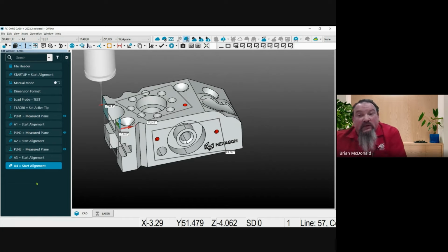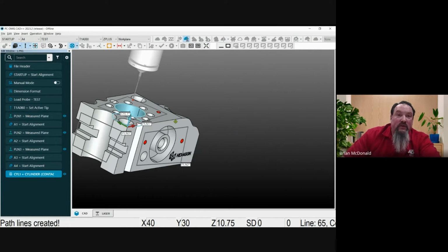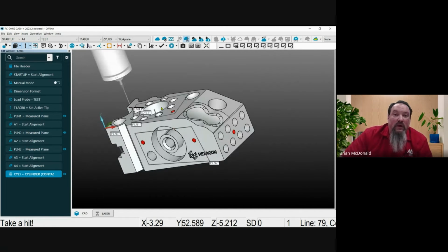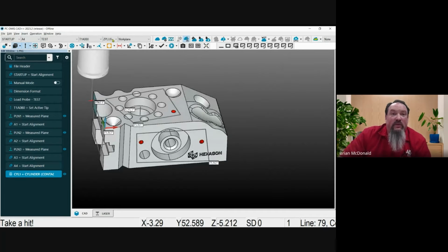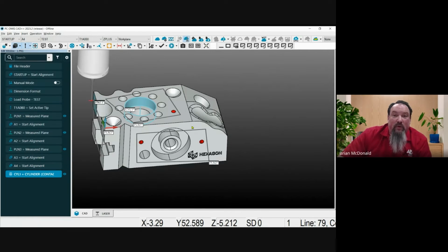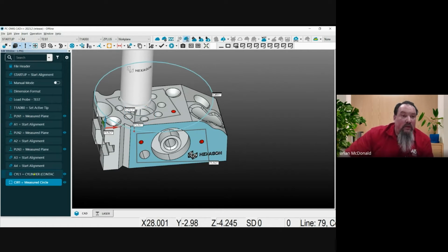The question is, can we use auto alignment with only planes, or can we use it with points, lines, and planes? You can use it with anything. If we go in and we use a cylinder there, and we have a point over here, do something like that, and then we do an alignment, and we grab the cylinder. Let's do one more thing. Let's do a line here. Yeah, I got the point.